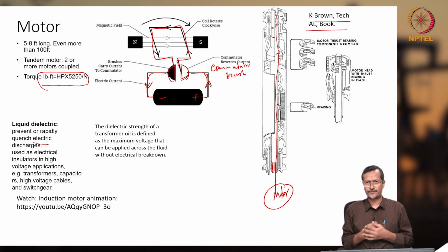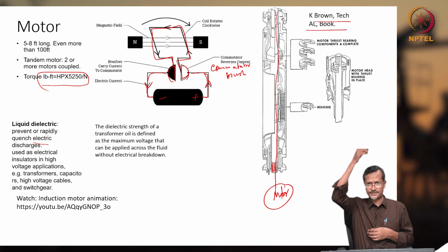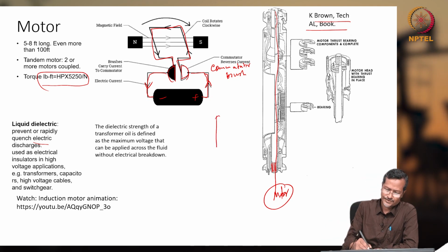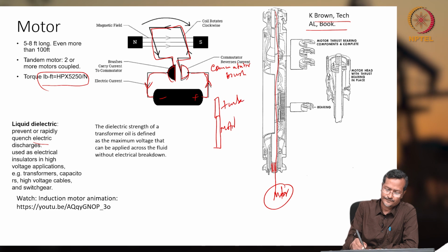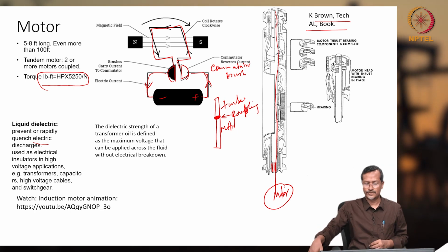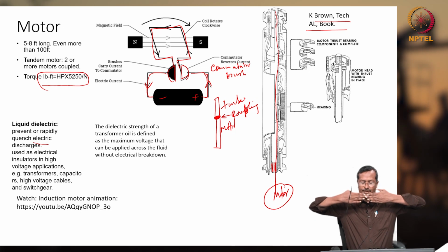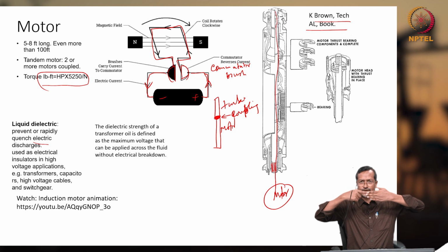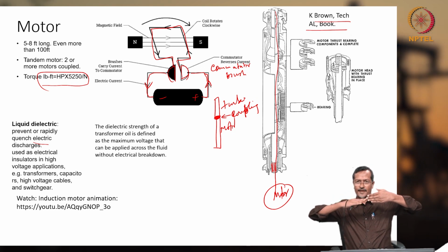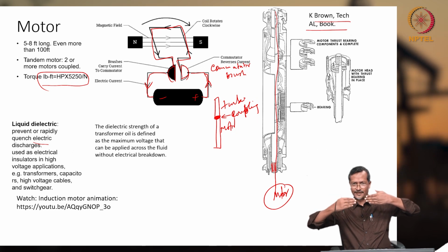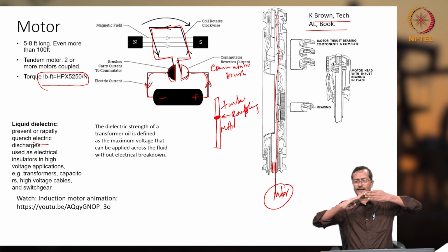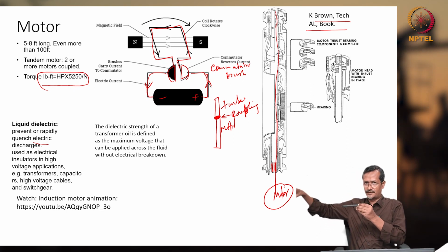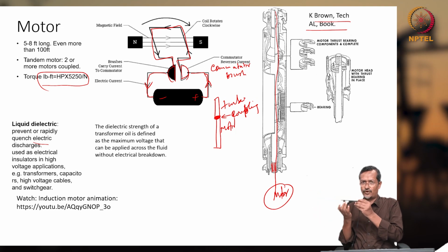When you connect two shafts, the main problem that occurs is alignment. If the shafts are not aligned, let's say this is the motor shaft, this is the turbine shaft, and there will be a coupling. If the motor and turbine shafts are not on a straight line, let us say one makes an angle like this, then when it tries to rotate, the turbine shaft takes torque from the motor shaft and rotates the impeller. Instead of straight, it has an angle like this, so the impeller shaft or pump shaft will have lots of friction and vibration.